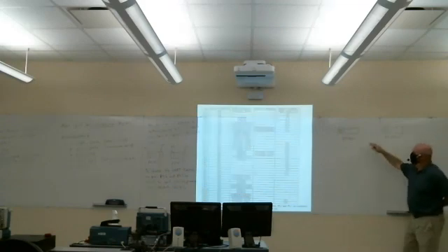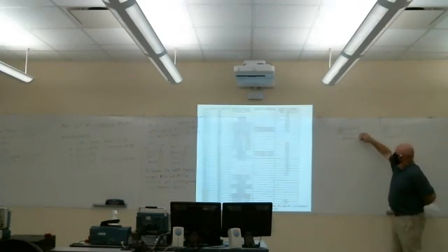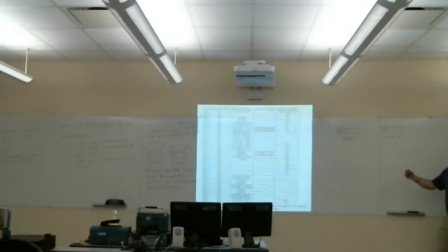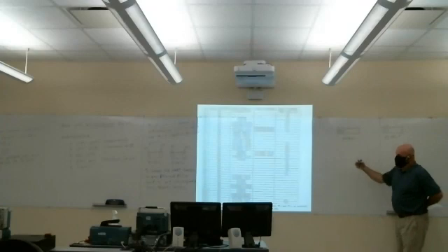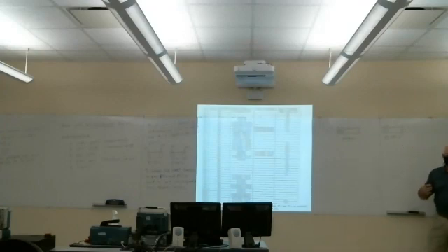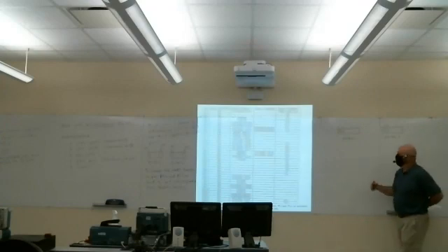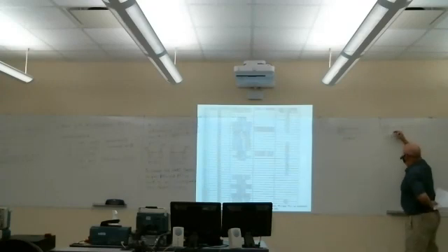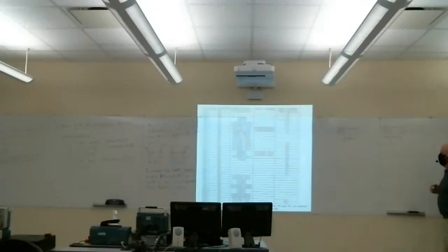An easy way to do this is essentially to write a binary 0 to that particular register address and set the whole thing to 0. But then that's going to change the function of the other pins. Especially in a long program, some of the pins may be assigned different functions, and you don't want to change the function. We only want to set those bits to 0 in the selection 1 register, and these 2 bits to 1 in the selection 0 register.